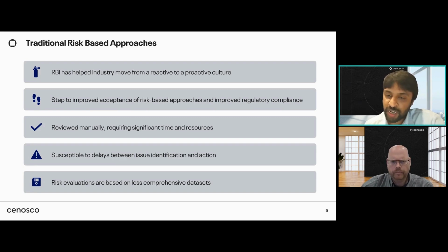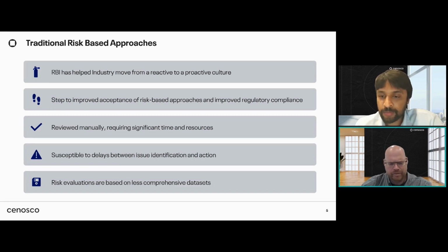So most organizations seem to assess risk based on a limited data set. That is typically where we stand as of today, Tomislav. The risk of relying on those limited data sets can happen on the side of having too high a factor of safety for some processes, resulting in inefficient extra inspections, or on the other side, where your safety factor ends up being too low, where you actually generate higher risk in your operations than is necessary.